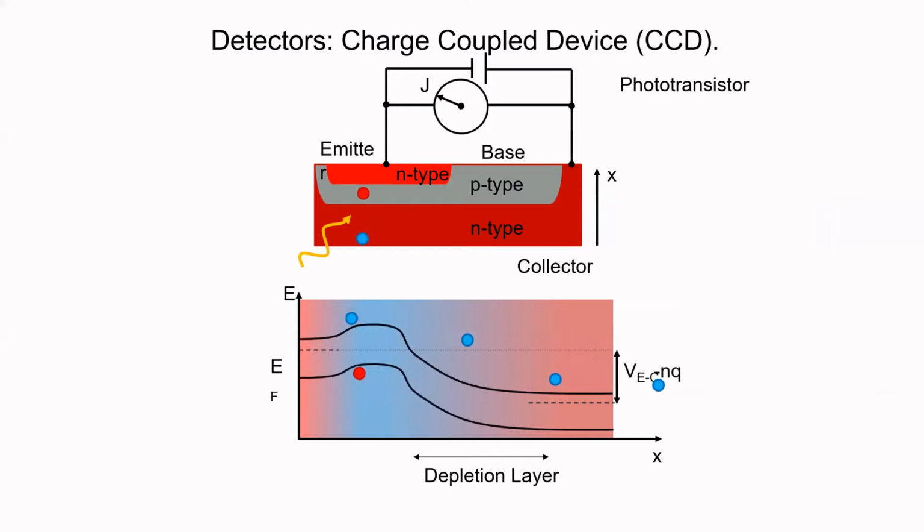So again, we turn it on, the electron is absorbed, and an electron and a hole pair are created. And then, as the hole moves into the P-type, that changes the potential of that P layer relative to the two N layers, because you're changing the occupation probability of the valence band there, as we've introduced extra holes. And so that shifts the Fermi energy relative to the bands. As a result, the potential barrier that was created is dropped, and all of a sudden you get this rush of N charge carriers through into the base of the device.